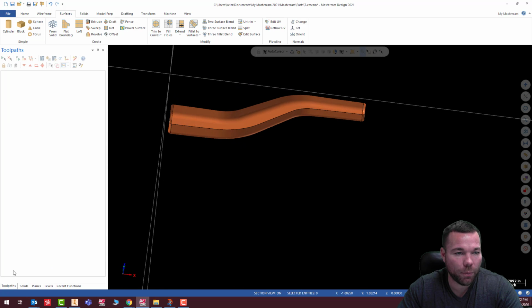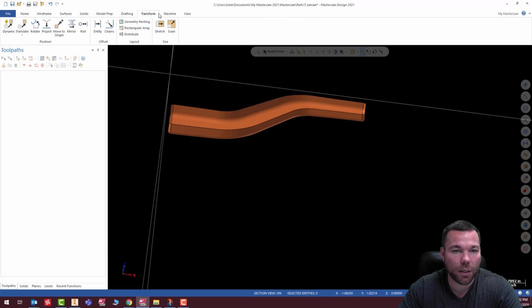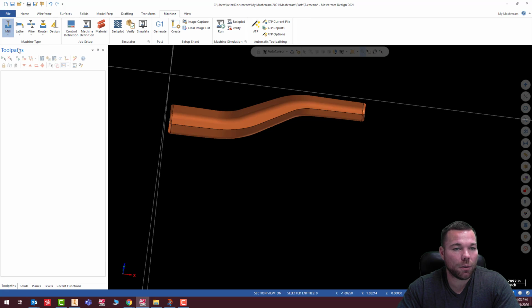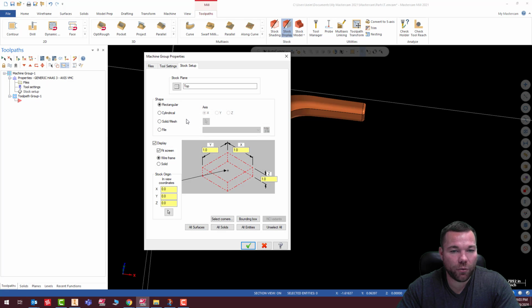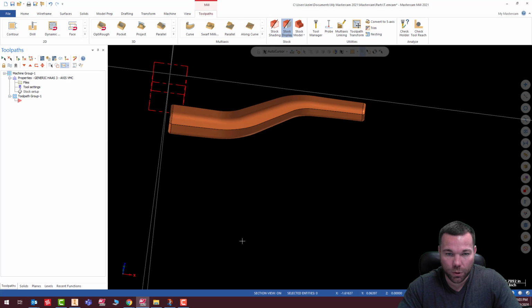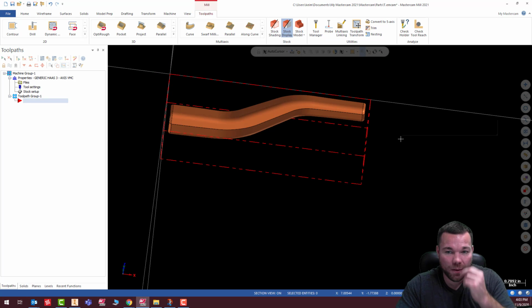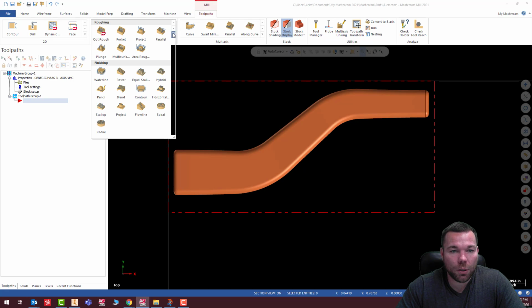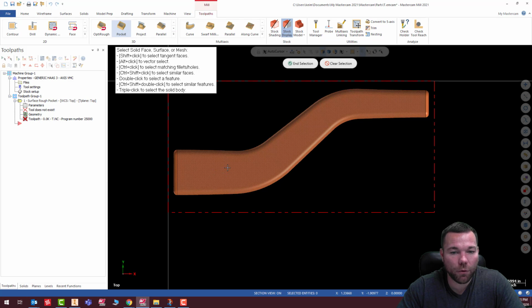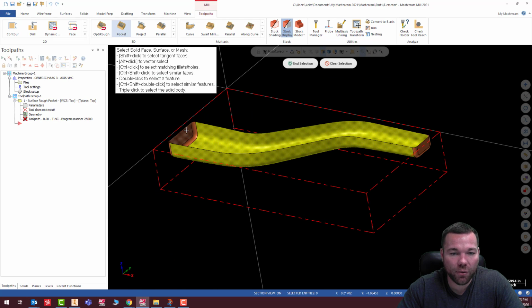All right, let's go back and let's pick a machine. Pick 3D Haas 3-axis mill and set our stock up. Leave our stock as 2.875 by 6.0, and we are up in the upper hand corner. All right, and that looks pretty good. Okie doke. So let's go ahead and we are going to do a pocket for this one. I'm just going to select this face.